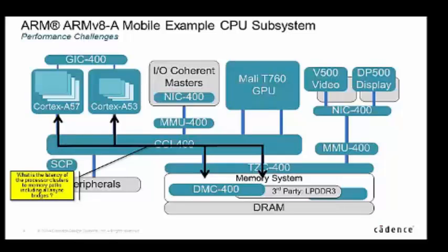It's not just finding performance problems, it's then how do you actually approach the debug problem? What other information do I need from my IP? For example, was the DDR controller doing a refresh when a particular transaction took a long time? That could be a very valid reason why a transaction takes longer than you expect.